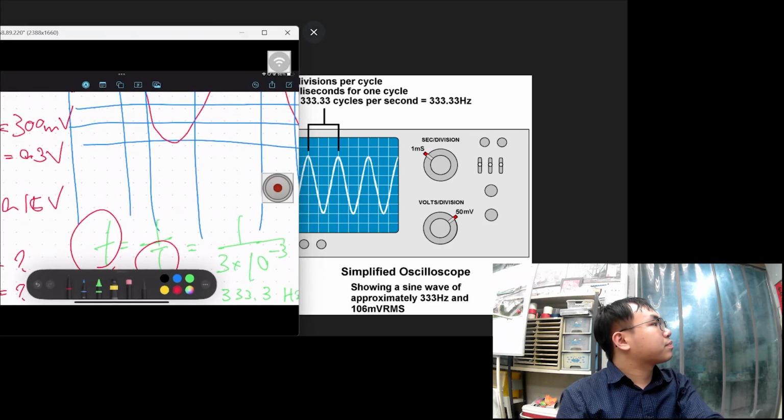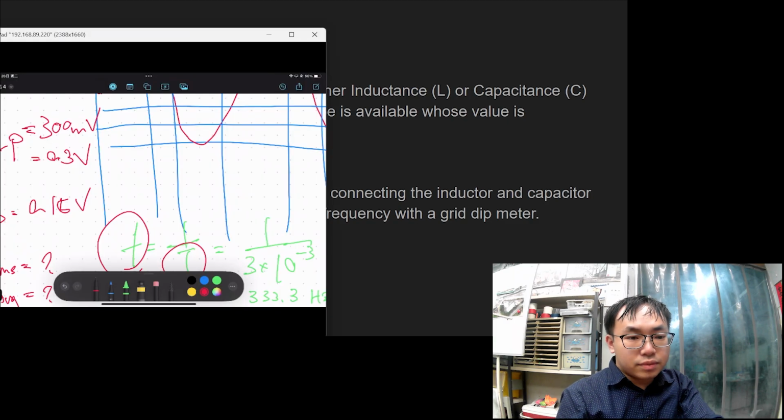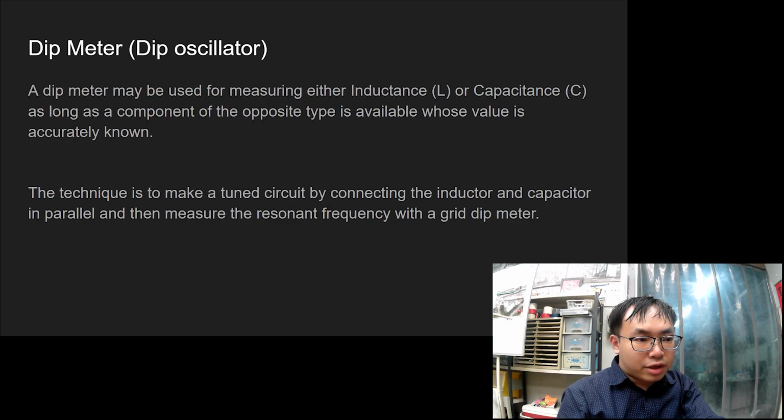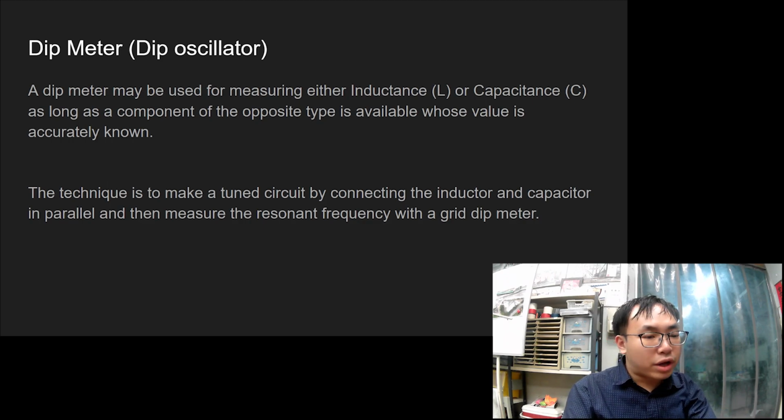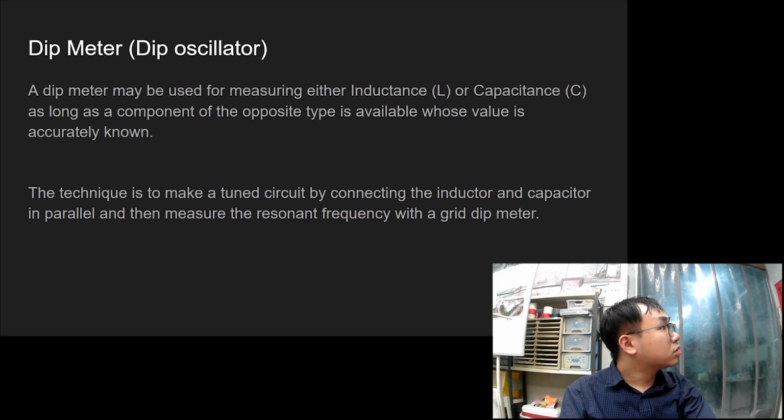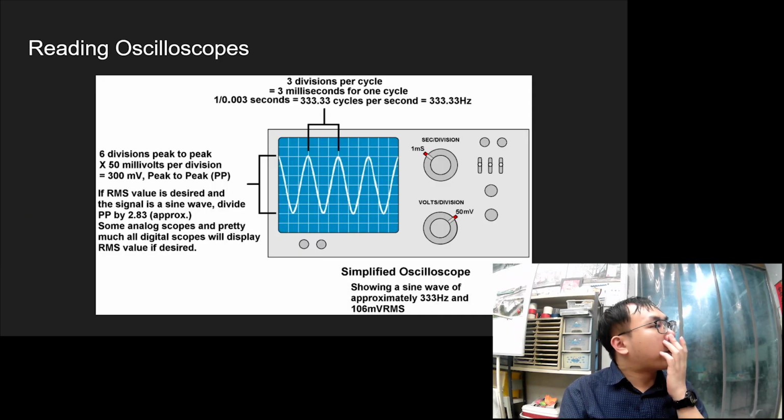Yes, correct. Just a minute, let me do 0.15 times 0.707. Yes, that's why when I have the example here, they talk about the RMS being 106 millivolts. That's because 0.15 times 1/√2 is 0.10605.